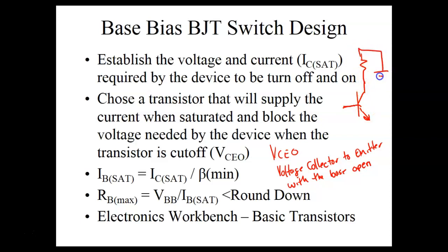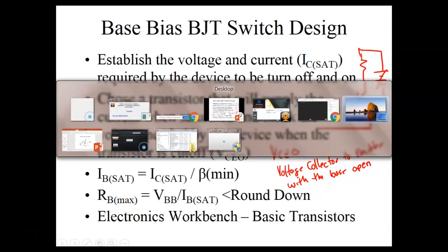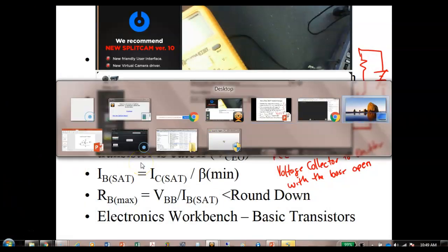If I start increasing this voltage, and keep increasing it, sooner or later I'm going to cause this transistor to conduct. It's going to be dropping a lot of voltage and it's going to burn up. This is kind of like the PIV rating on a diode. These are the voltages that you can reverse bias a junction with and not cause it to be damaged. So this is a very, very important rating. If I come back over here and look at my data sheet again, which I've already closed out, there are some ratings in here.